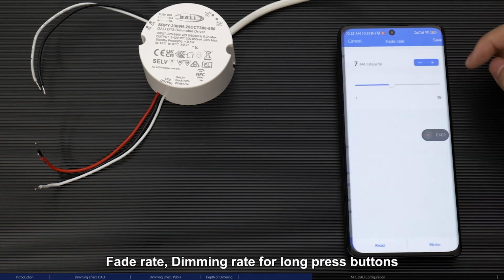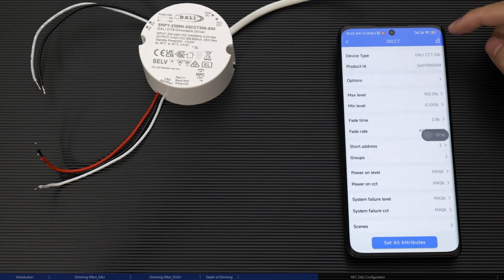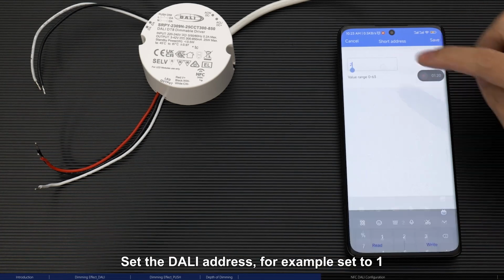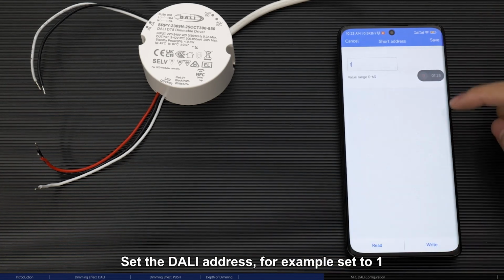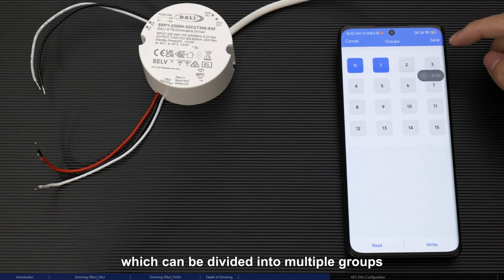Fade rate, the dimming rate for long press buttons. The default value is 7. Short address. Set the DALI address, for example set to 1. Groups. Set up grouping, which can be divided into multiple groups.